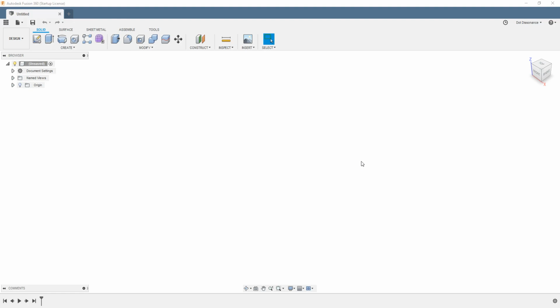Now, the other reason, for you non-KiCad people, that you would want 3D design shapes, rather than just to look cute inside of your EDA program, is that you want to know the height and the sizes of these things so that you know if they're going to fit inside of your package envelope, as in the box or thing that you're putting it into.